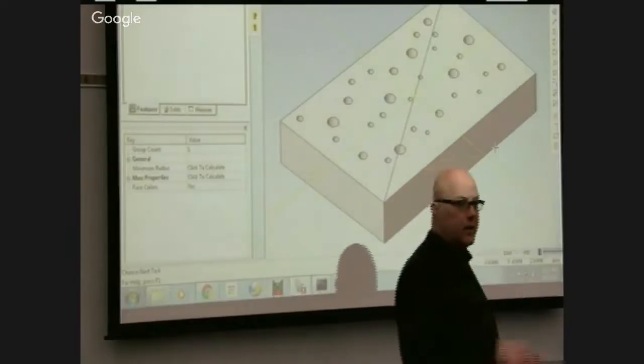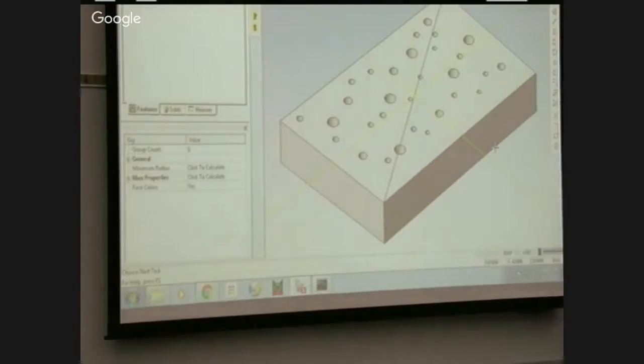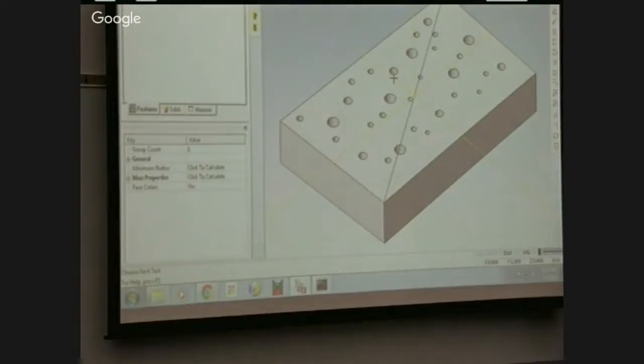And you had one other way to do this, right? Line based. Yeah. And so let's say we actually wanted it to be on the bottom. When might I want the origin to be on the bottom? Top of rough. If we're going to do a facing operation on the top of the workpiece and we care what the thickness of the finished part is, we want the origin to be on the bottom.